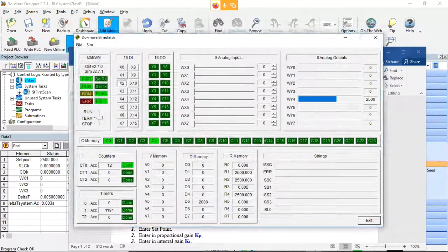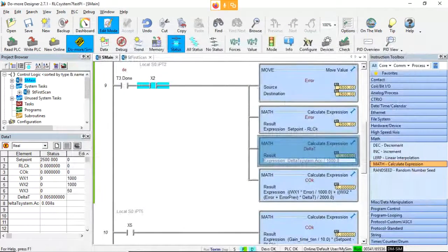Okay, but what we're going to do is, I would recommend you start with the slow system, because slow systems are easy to work with because they don't blow up so quick. This fast system is really bouncing around as it is, so it's going to be very touchy to get the gains correct. If you get too big of gains, even with a derivative gain, if you make that derivative gain too big, instead of settling the system down, sometimes it'll actually drive the system unstable.